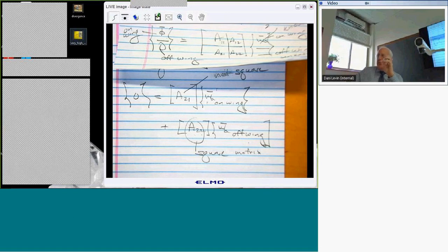The pressure at the leading edge, according to this theory, goes to infinity if it's a subsonic leading edge. Even though we're in a supersonic flow, there is such a thing as a subsonic leading edge, meaning that if you look at the Mach number normal to the leading edge, not the free stream Mach number, it can easily be subsonic. That component can be subsonic. When that happens, it turns out that the pressure at the leading edge goes to infinity. This is well known in subsonic flow, and it happens in supersonic flow too, depending on what the Mach number is.